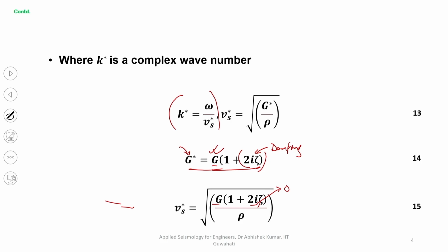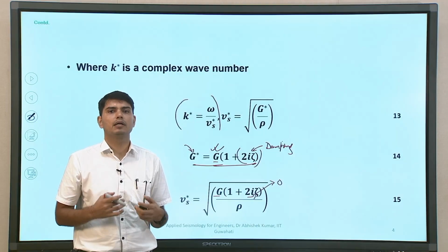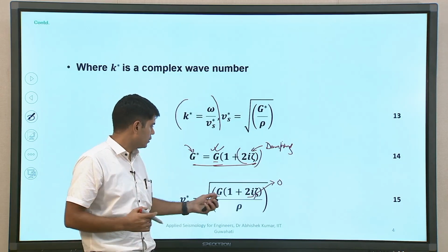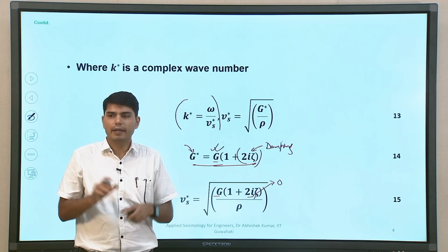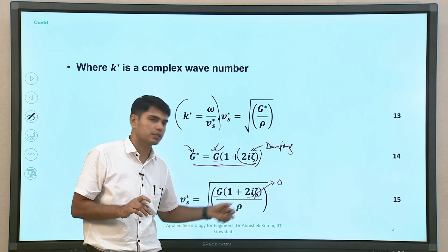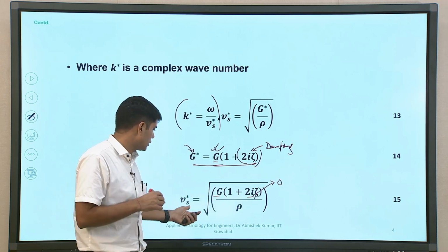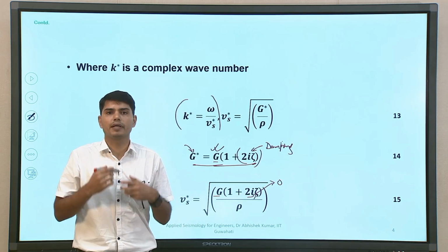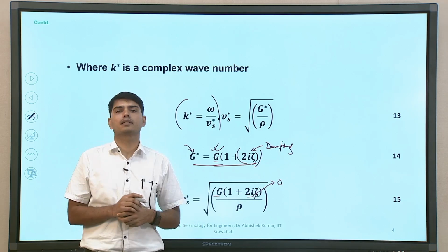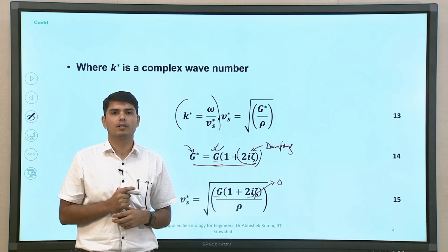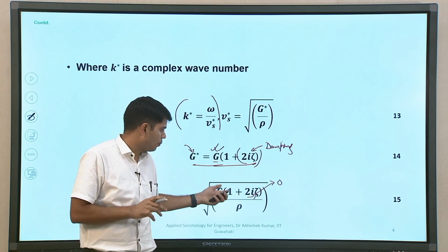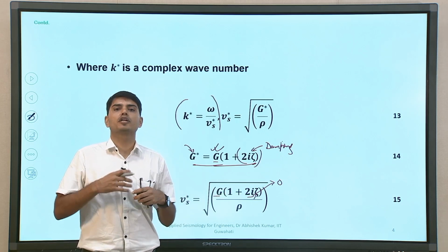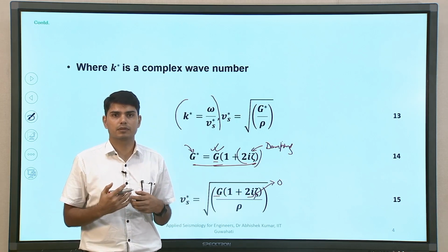Being dynamic, depending upon how much shear strain is mobilized by the external loading condition will define how much the shear modulus will be and how much the damping ratio will be. Collectively, the combination of shear modulus and damping ratio will determine how much resistance the soil is going to offer due to the external loading condition. When we discuss this further, we will also see how a particular soil layer responds differently during different earthquakes.